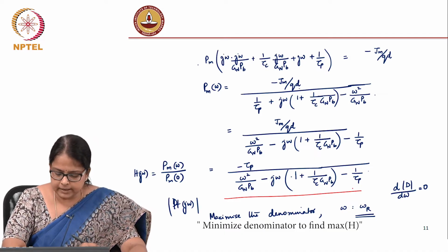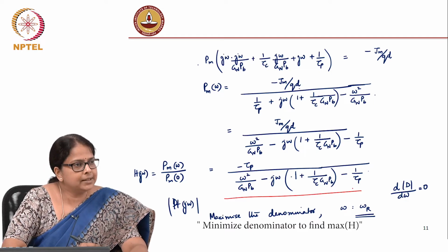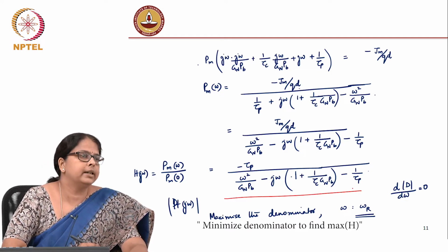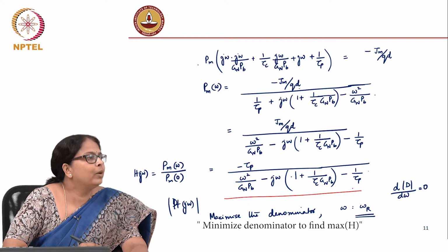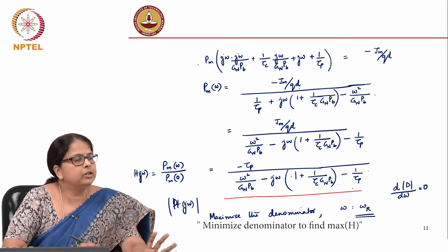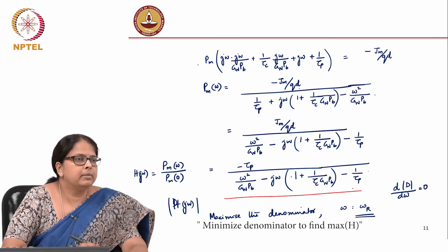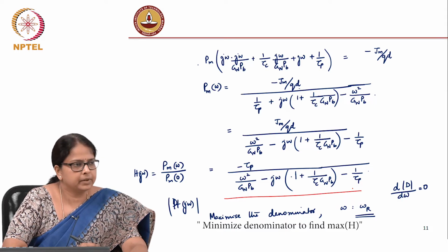Okay. And what we are interested to know is that, of course, in case of LEDs, we found this was like a low pass filter. There was only one term, a j omega term, in the denominator, and that was immediately looking like that of a low pass filter. And we said, okay, the response is characterized by the recombination time tau c.